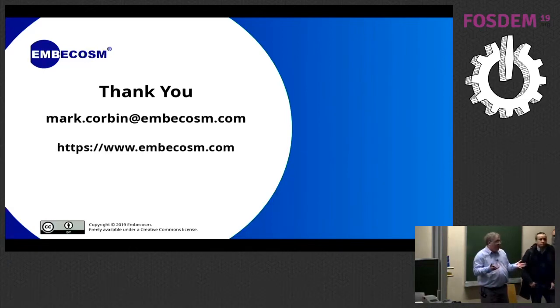I don't know whether Yocto easily produces smaller libraries, quick and fast systems. I see Yocto as adding a more powerful system that you might want. I think it's partly my background in smaller boards, lower resource systems. I see Buildroot as sitting towards that end of the market, and Yocto sitting perhaps for more powerful applications, more flexible systems that need more features. You'll find a lot of talk on the internet about comparisons between the two, and I think they are two different beasts for two different things. Does that sort of help?